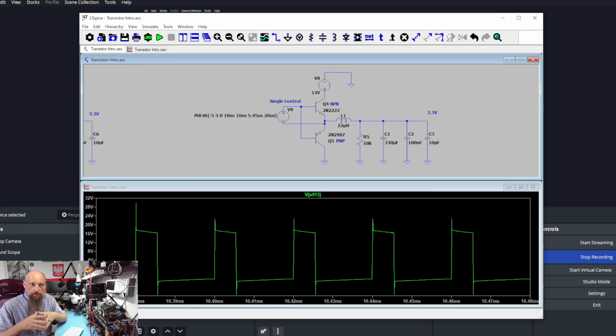The best way to measure the transistor in circuit is obviously to connect to collector and emitter, or drain and source, and to see what the resistance is. If your meter beeps showing that the transistor is shorted, it's not a definitive answer that this particular transistor is shorted.